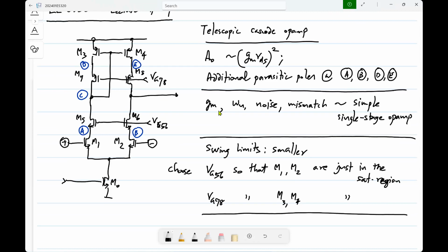No, if you assume perfect symmetry, they will be the same. In practice, because of mismatch, if you just bias it without DC negative feedback, it will be in the upper saturation or lower saturation. That's the likely solution, right? No, see, the output voltage in an op-amp circuit will be decided by the feedback, right? And what input you apply. So it is going to go to that.